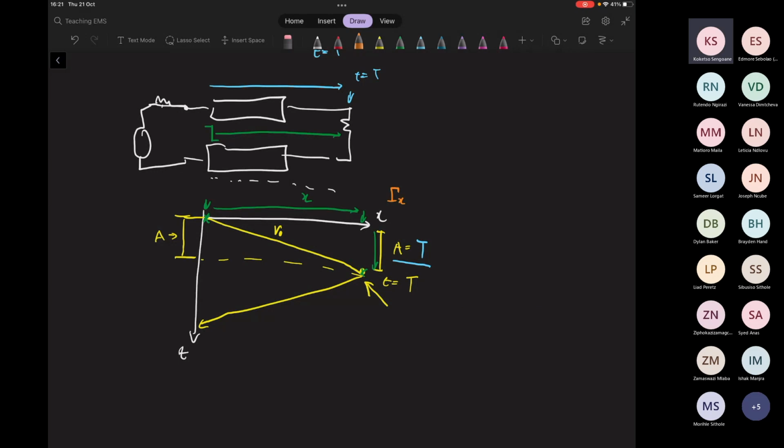Initial multiplied by the coefficient. Yes, it'll be the coefficient. This is the reflection coefficient that tells us of the incident wave, which is this initiated voltage. That's this one here. This is the incident wave. We times that incident wave by the reflection coefficient. Exactly. So now if I were to say what is the voltage over there, it would be the sum of the waves that are present there. So it'll be that plus the reflection coefficient times V naught, like that. So it'll be the sum of those two things.